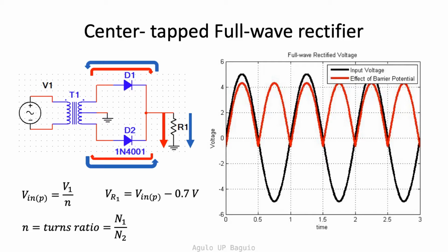If you use a multimeter, you'll measure 220 volts. That is an RMS or root mean square voltage. It is related to the peak voltage by a factor of square root of 2. At the primary coil, it is still 220 volts, 60 Hz.